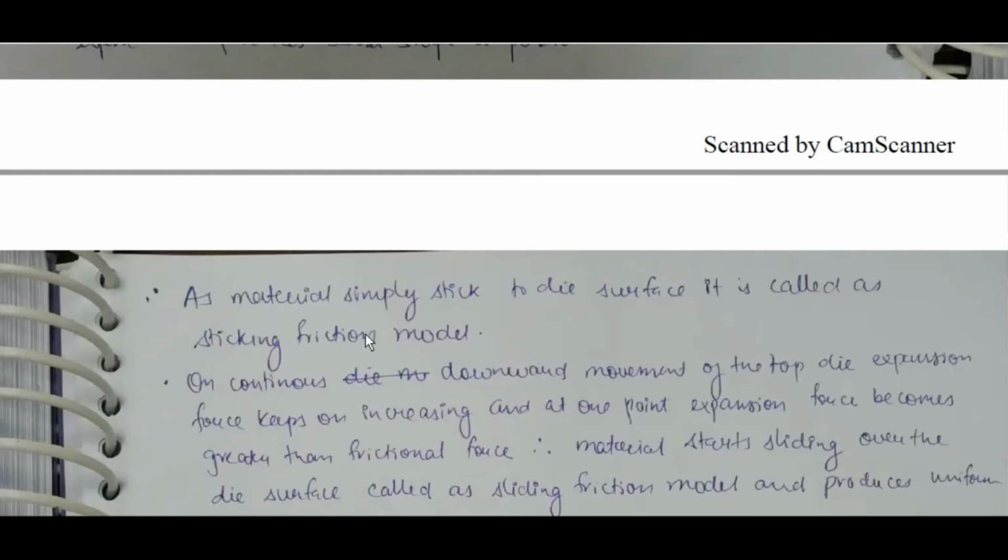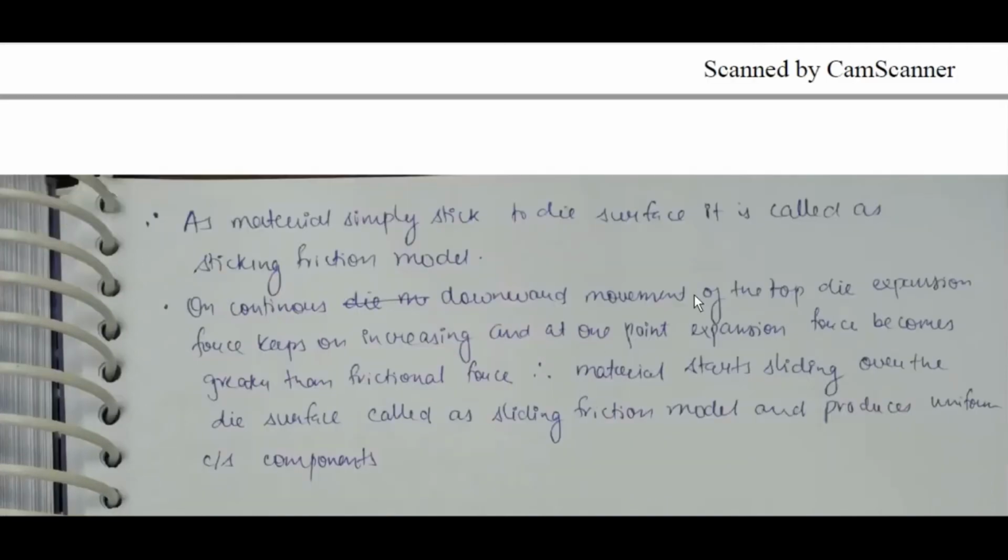The material in the flash land is also wastage which is cut by the trimming operation. The material in the gutter and in the flash land provides an extra cushioning effect to the material in the forging cavity.